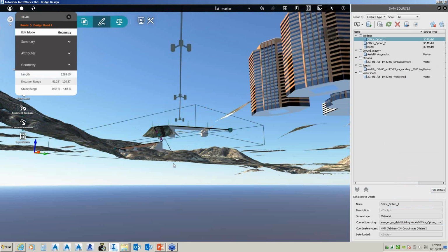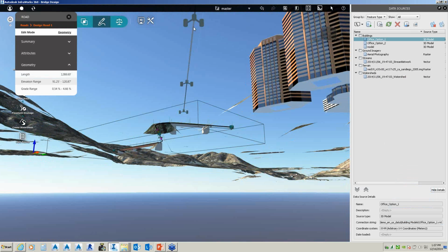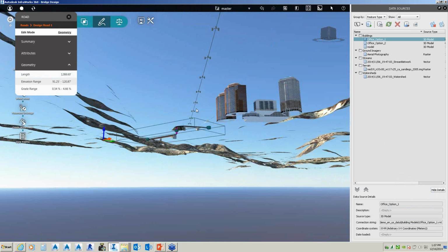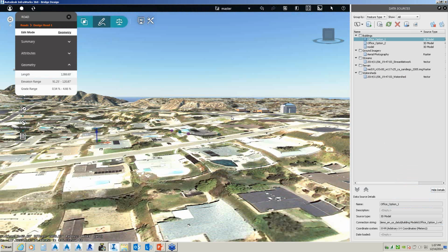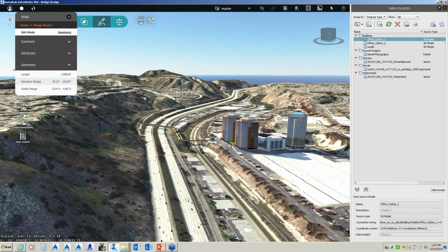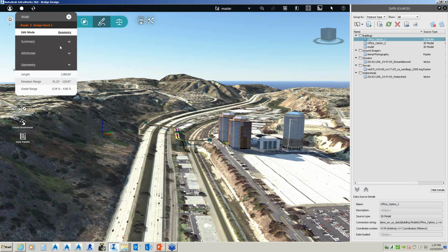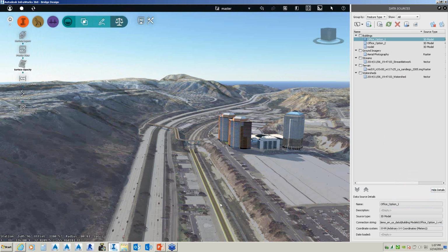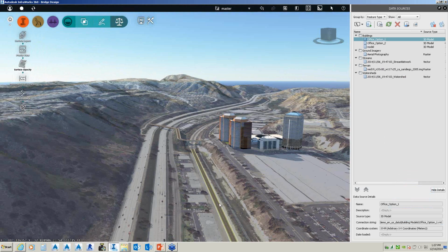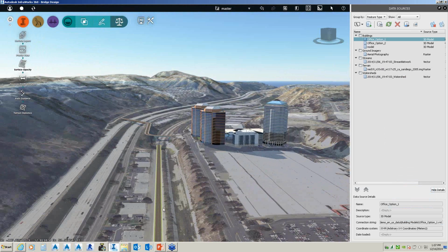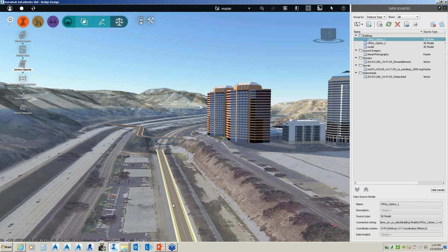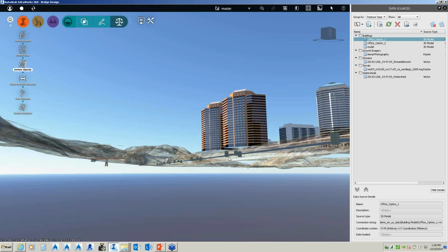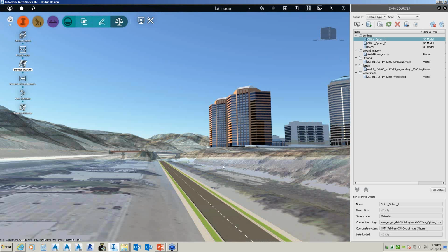And as you can see on my road here, my storm network has been created for that road. So we're just going to zoom out a little bit. And then for purposes of visualization, we can come right here in our drainage network and I can change my surface opacity. So then when I zoom in, you can see that it's created a drainage network for me.